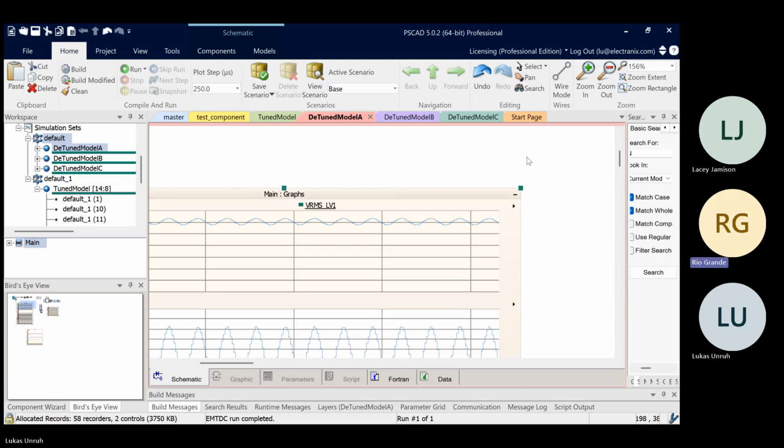Right, so I'm just wondering, if we have a weak part of the system and we're building a new line out to it, with generators out there tuned to the low SCR, we may need to work with those guys to adjust the settings potentially, if you're strengthening. Yeah, what I heard you say is that if they were tuned to be stable in a weak system and then you make the system stronger, they're still going to be stable. They're just going to be slower. Okay, still work with them.